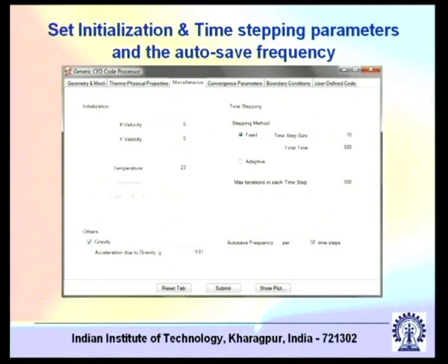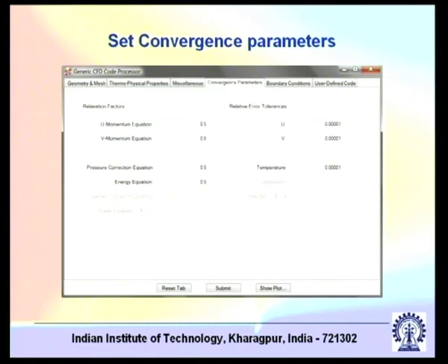You have to understand what is there inside the code. Maybe inside the code gravity is already implemented along negative y. That is why do not try to use a code without trying to at least understand superficially what is there inside it. Otherwise you can make mistakes by considering some values which are not consistent with what has been put inside the code.